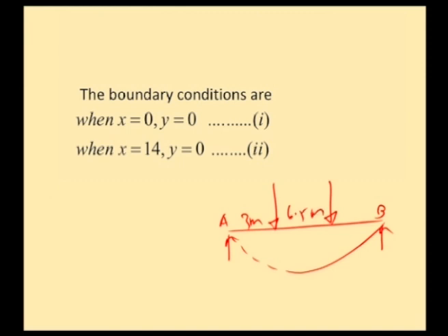So, we need to substitute x equal to 3 meters if I am interested in finding deflection at C, and I will have to use the general equation for deflection up to the first dotted line. If we want deflection at D, I will have to use the general equation for deflection up to the second dotted line. So, that indicates where our point of interest lies.